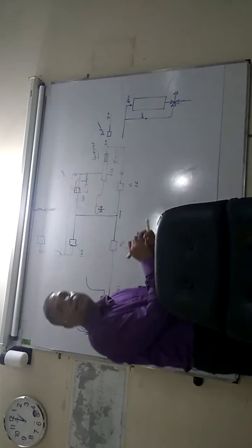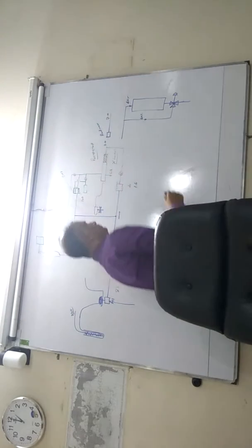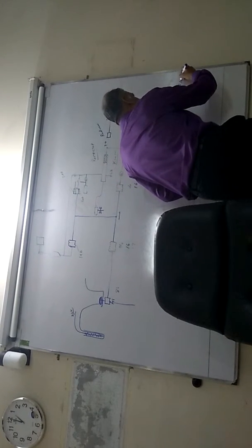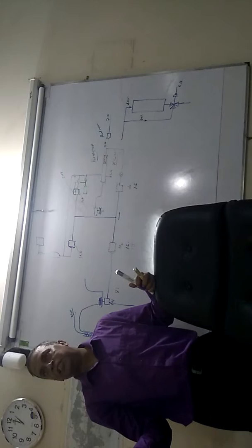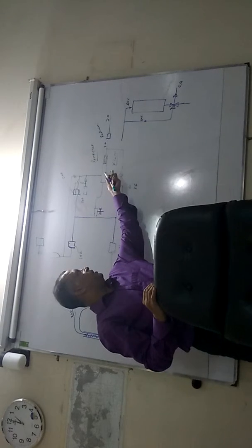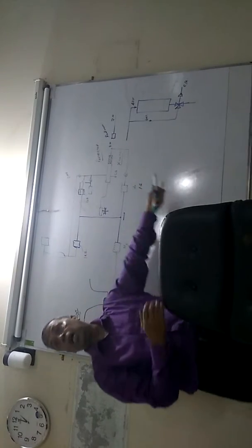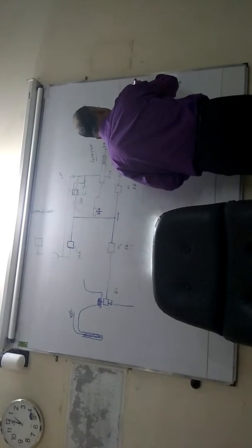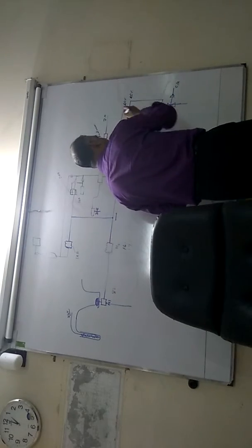Okay, understand? Now what happens is this corrective action signal is going right on top of this diaphragm operated valve. Okay, now there is a certain increase in this pressure, right? Because air cannot bleed out, so the pressure here is increased, so that the pressure on top of the diaphragm will increase, and the result is that 45% now water enters the cooler and 55% of the water now bypasses.